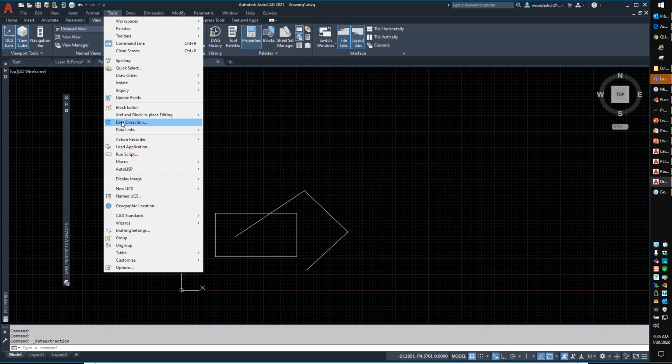How does the project command differ from the flatten? You're talking about the project command differing from flatten. Flatten is to flatten everything out to 0. Flatshot is to grab all 3D objects and create 2D blocks from 3D objects, and the project command allows you to project into a different Z elevation.